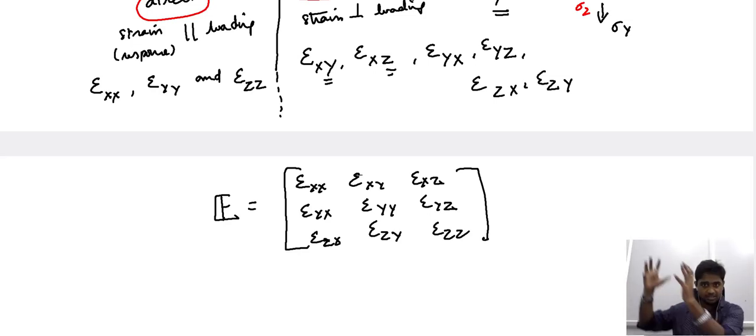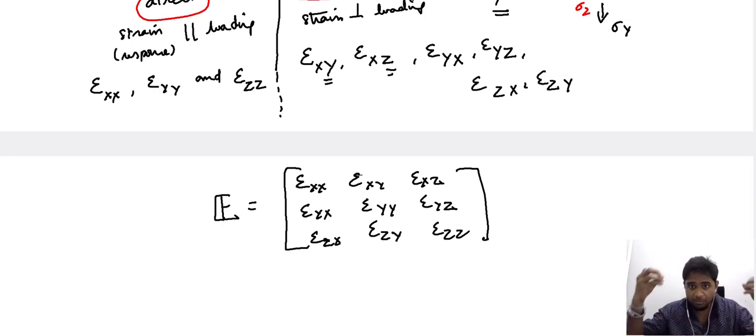So we started off with the triaxial loading condition and ended up with this matrix, or tensorial, representation. From a purely numerical perspective, it is easy to start from this and express the overall strain the material exhibits based on its loading condition. If you consider a simplistic loading condition, then certain terms will assume the value of 0, and the matrix will be a simpler, straightforward matrix.